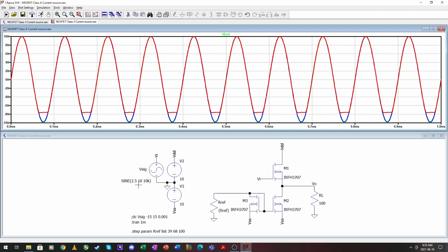Okay, so you can go quite far with a MOSFET Class A amplifier and be more efficient if you do a voltage divider or some other form of reference right here. And having the offset added automatically here at the input side would be quite easy with the MOSFETs. Just have some huge resistors there and you can sort it quite easily.